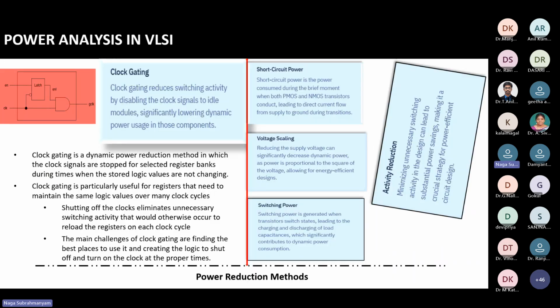So these are the various techniques to reduce the power, somehow manageable, which are called clock gating. Means as soon as the clock requirement is done for a particular subsystem, we have to control the clock to that particular block. Why do we need to control the clock? Can anybody answer this?